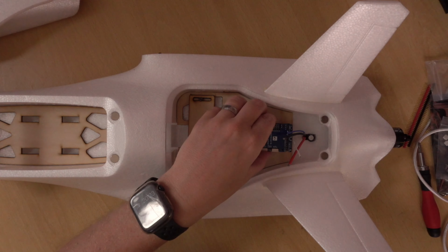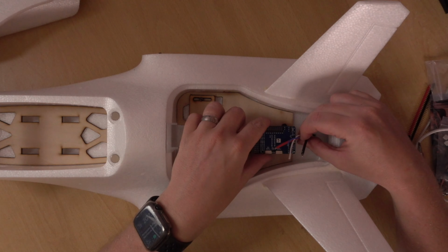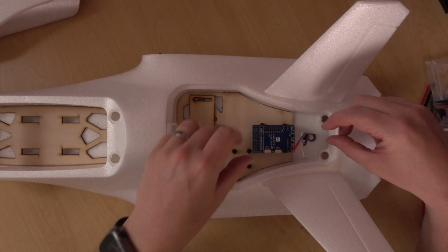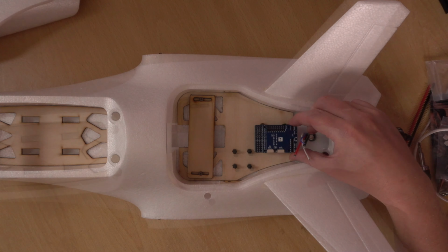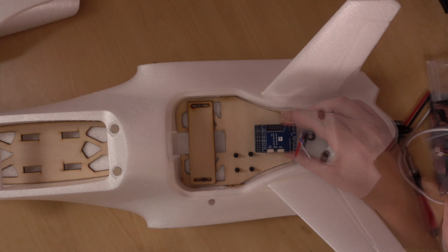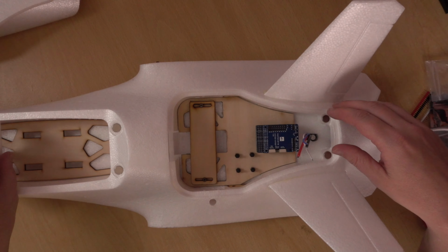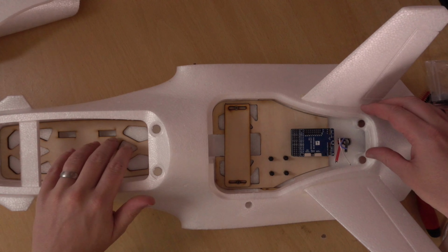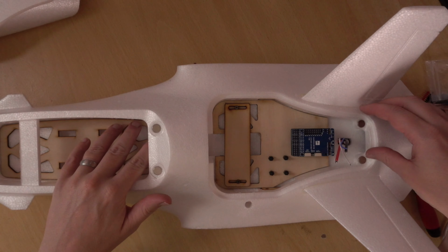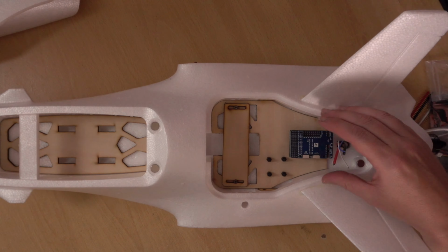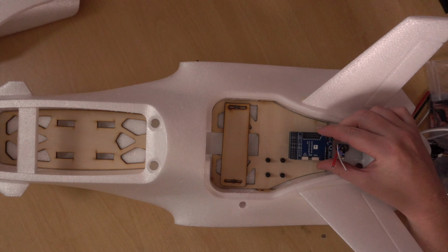Now I know that I want my flight controller to go right here. The reason I want that is because then it will be a nice simple connection for the ESC. I could actually chop these cables down a bit, but also it gets it back out the way. Obviously we need to get the CG right, but the weight of the things in the back are going to get easily compensated for by putting batteries in the front. I'm going to be using probably a 2200 4-cell for this, so I will probably need to have that quite far back anyway. So what I'm going to do is aim to have more weight towards the back than at the front. So what components do we actually need in here?